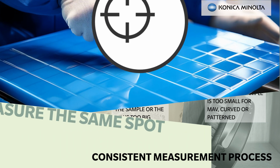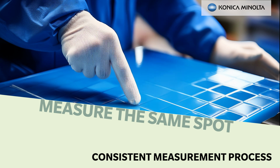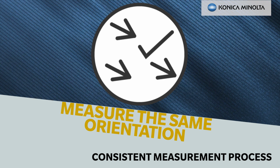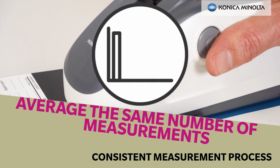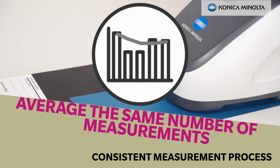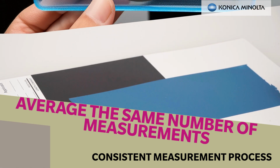When you measure samples, you should do so in the same way. This means measuring basically the same spot on the sample, with the device orientated the same way. You can agree with your supply partners if an averaging of 2 or more measurements is made, and what the measurement or escalation process is if a sample falls outside of tolerance to the target.